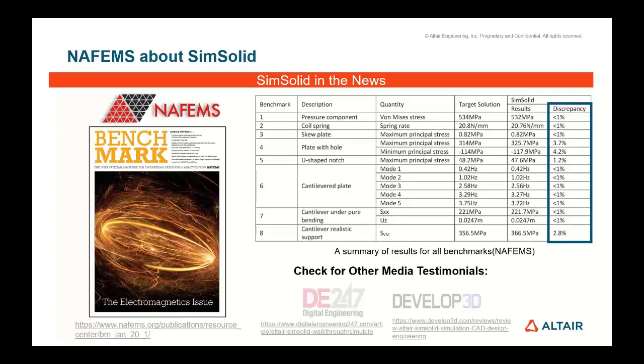Then which type of CAD file format works best for importing? Do you have an experience there? Well, SimSolid is a CAD agnostic software, meaning it can read in any CAD file format, even native ones like CATIA V5. I always go by STEP or Parasolid. They work quite well for me, but they're just the ones that I have available.